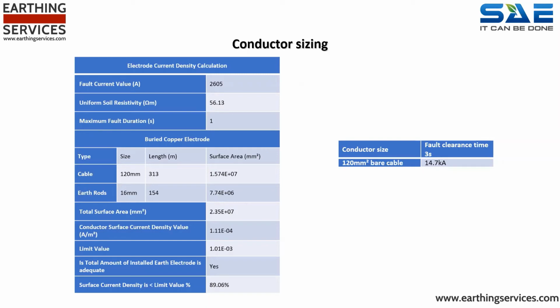Earthing conductors must be selected from standard copper section, which has to carry the full fault current from the point of fault to the main earthing system. It is recommended that the value of current rating to be taken is that corresponding to the ultimate system maximum symmetrical 3-phase short circuit current. Subsequent redistribution of these circuits into 2 or more paths allows a reduction in the size of the branch conductors.